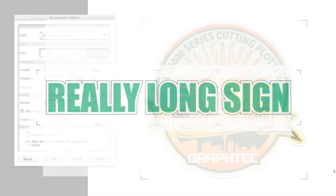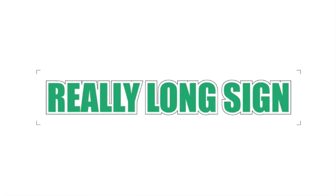When cutting longer designs, there's another option of using what is called segmented registration marks. This is where, along with the registration marks on the four corners, there are registration marks that look like little T's between the corner registration marks, as you see here. Segmented registration marks are used by the cutter to determine if any bowing has occurred during the printing process.